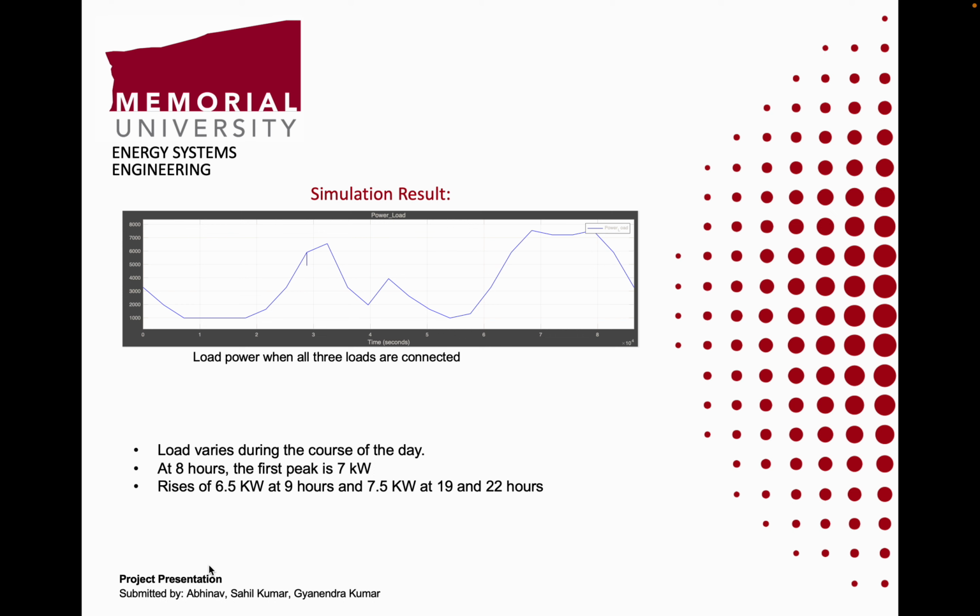So from this simulation result, we can see that from 0 hour to 12 hour and from 18 hours to 24 hours, the battery control is performed by the battery controller. The battery control performed tracking control of current, so that the active power which flows into the system power from the secondary side of the pole transformer is set to 0.